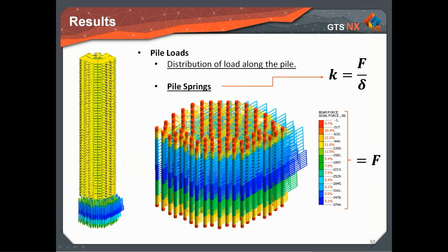So we can calculate springs. Those springs are different for each pile. The reason for this is mainly because of the position of the pile inside the raft, which can be affected by the location of the column, due to pile group effect, which tends to decrease the performance of the pile, meaning that some may not offer the same reaction as others. So the generated springs for each pile may be sent to the structure team or simply exported back to MIDAS Gen.